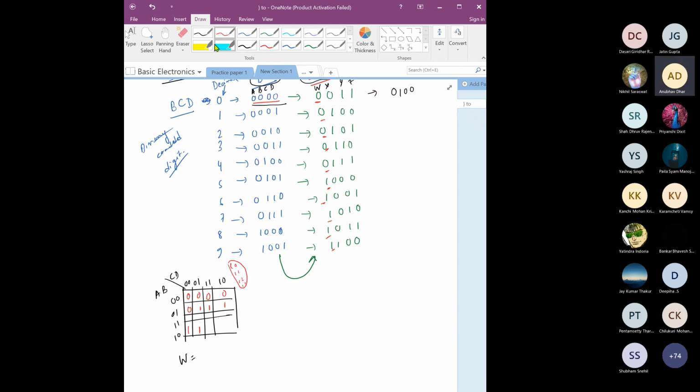So we can put any of the 0 or 1. These combinations are called the don't care combinations. Don't care combination means this: we will make sure that in this BCD number, for example 1 0 1 0 or 1 0 1 1, this will never happen in the input. As these are never going to happen, we do not bother about what the corresponding output should be.